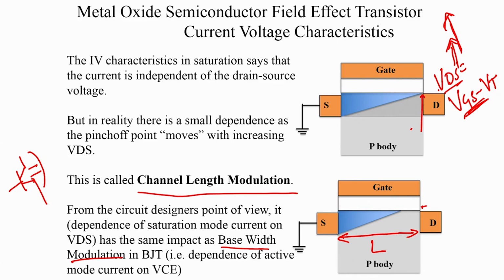And we saw that the current versus VCE did have a small trend even in active mode operation. It's exactly the same situation here.